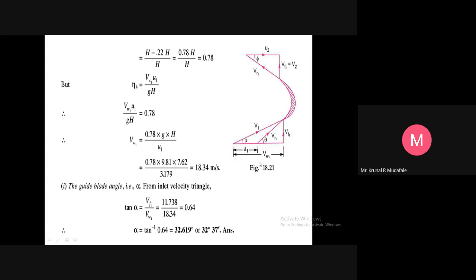two components vf1 and vw1, okay, at the outlet section. Because of the absolute velocity first striking the blade, obviously at the outlet section there will be a relative velocity that comes out. So the angle of the relative velocity at the tip, at the outlet, is phi, okay.